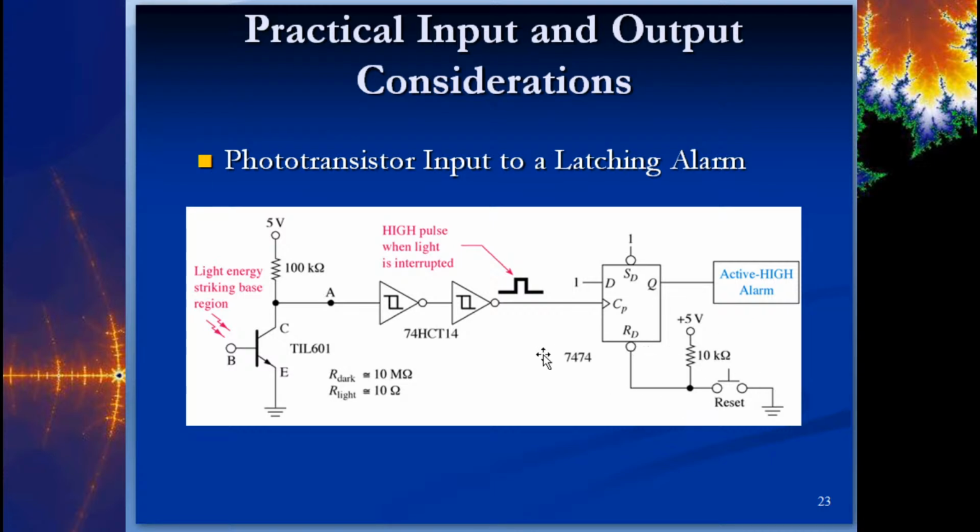So this transistor, and this is not an analog class, but anyway, if you have sufficient current on the base, it will provide a short from C to E. And essentially you can drain current through there. You can sink current through there. We talked about that in Chapter 9. So this is a photo transistor.